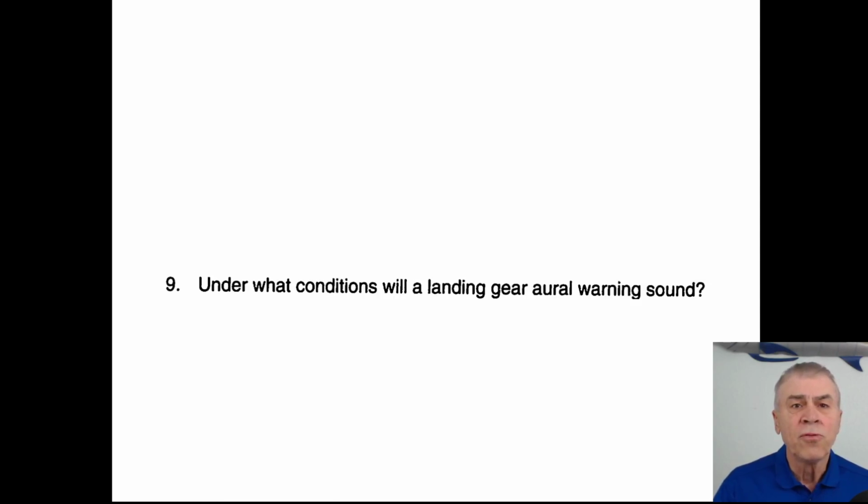Under what conditions will a landing gear aural warning sound? A very similar answer to the correct option in the multiple choice, and that was any gear not down and locked with any throttle retarded.